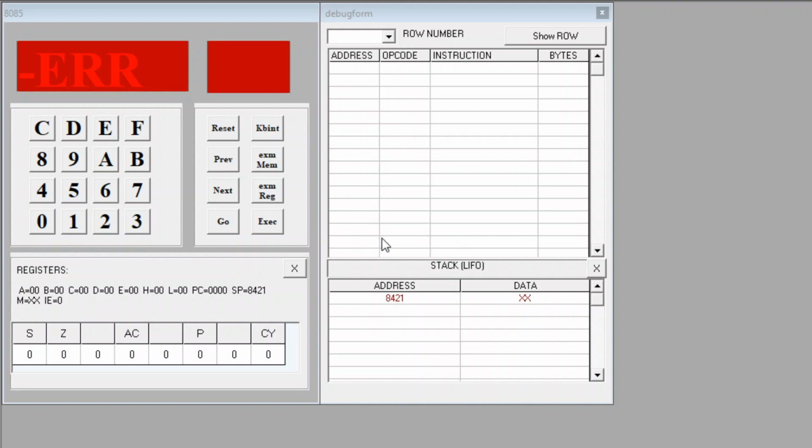So it is reserved for internal memory for processing by the ROM, and for the user only 8000 to FFFF is available. Fine. Maybe you are not able to see this right now, but once you try to access those memory locations, you will receive this error code.